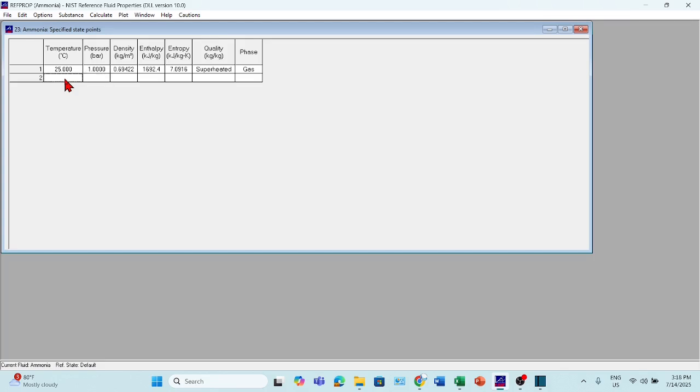If you are working on a vapor compression cycle or some refrigerant and want to know the 4 or 5 state points, like in the evaporator, after compressor discharge, in the condenser after subcooling, and after expansion, you can just put in the temperature, pressure, or quality values and you will get all the state points. For example, in the evaporation, let's say the evaporator temperature is -10,